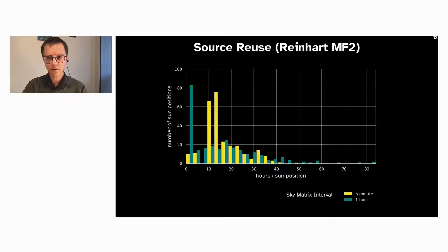For hourly data, there are about 200 patches representing around 4,100 hourly sun positions. For the 5-minute data, 250 patches represent around 2 million sun positions. The extra burden on simulation here is small, only 250 divided by 200. And in fact, since many implementations do not pre-filter the sun positions, there is effectively no simulation cost. But 2 million time steps would be a significant burden for the post-simulation calculations.